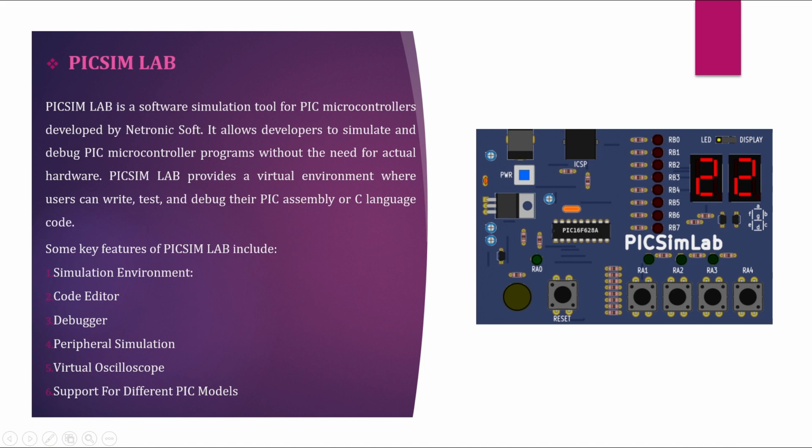So the second software is PIC Lab. PIC Lab is a software simulation tool for PIC microcontrollers developed by Neutronic Soft. It allows developers to simulate and debug PIC microcontroller programs without the need for actual hardware. It provides a virtual environment where users can write, test, and debug their PIC assembly or C language code. Some features of this include simulation environment, code editor, debugger, peripheral simulation, virtual oscilloscope, and support for different PIC models.